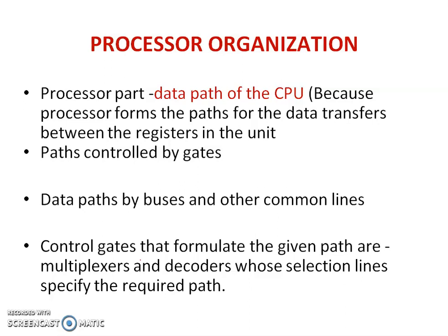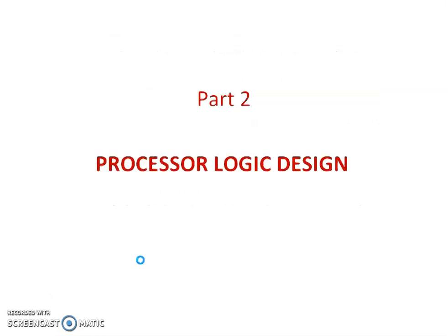decoders, depending on the function of each, what the multiplexers do and what the decoders do. As we have seen, multiplexers help to choose the source. The source will be chosen and the data will be placed on the bus. Decoders choose the target, that is, from the bus, how the information is loaded to the target. Those things we have seen in the previous classes.